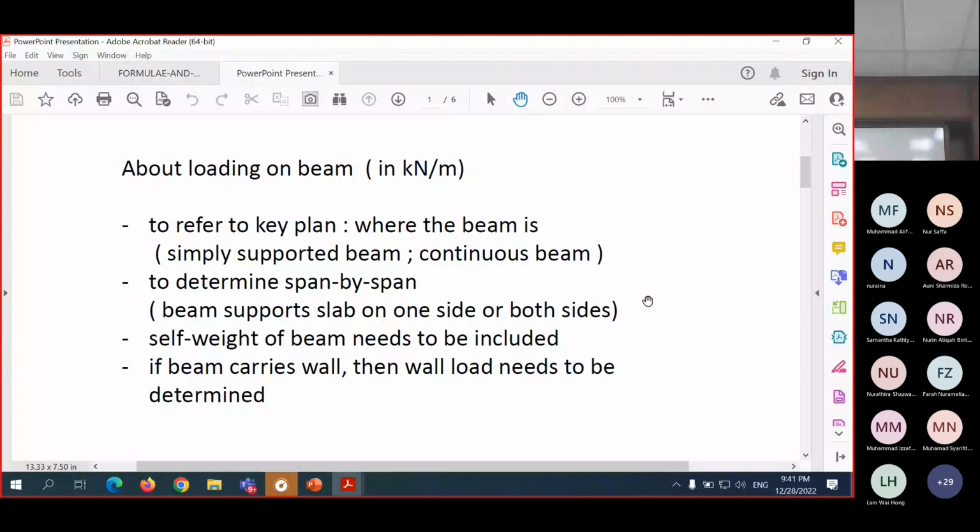Now for lapping, in your design project you do not have to specifically consider lapping. But lapping, of course, in actual cases will mostly happen because, as I mentioned, the bar length cannot satisfy the length that we want. We have to use a bar of certain size and then lap them.